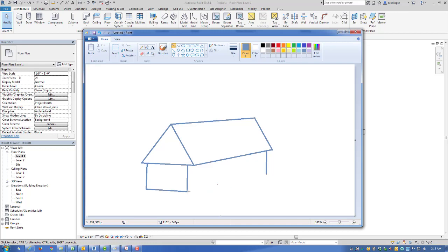Well, Revit takes this model, this 3D view, and if you wanted to see an elevation, Revit defines the elevation as looking at from this point and looking directly at the front face, or whichever face. Similarly, if you're going to ask Revit to show you a floor plan view, Revit will take a cut through the building 4 feet above the level and look down from there.